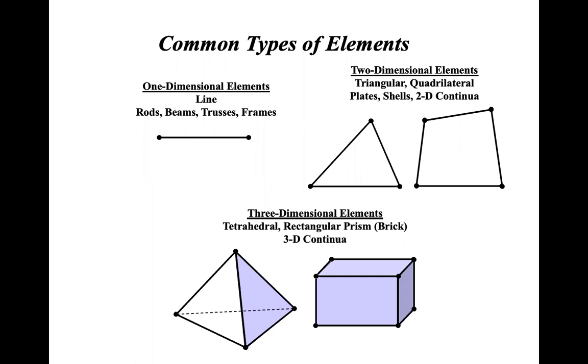But when to consider it? Whenever our geometry is complicated and all the dimensions are important. Like we cannot assume that our thickness is much smaller as compared to length and width. If thickness, length, and width are all important, in that case we can go with solid elements.